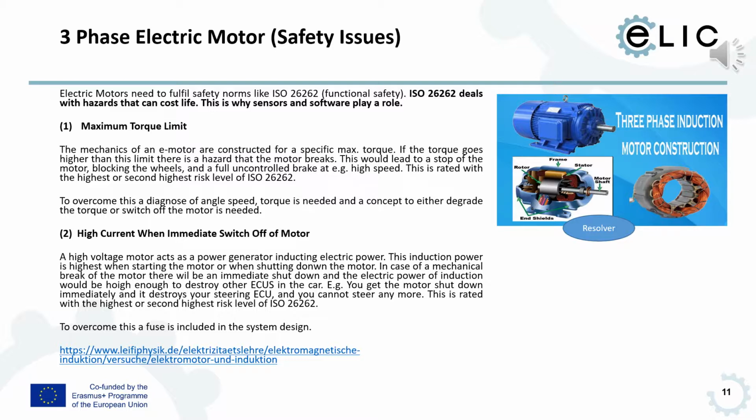This is safety critical because if the motor would break, it would block the motor and later block the wheels, and it comes to uncontrolled deceleration of the vehicle. The other thing is that you have induced power, induction power, and when you decelerate very much, which means we have a high current, when we have an immediate switch off of the motor during drive, this current could be big enough so that it destroys other electronic control units in the car.